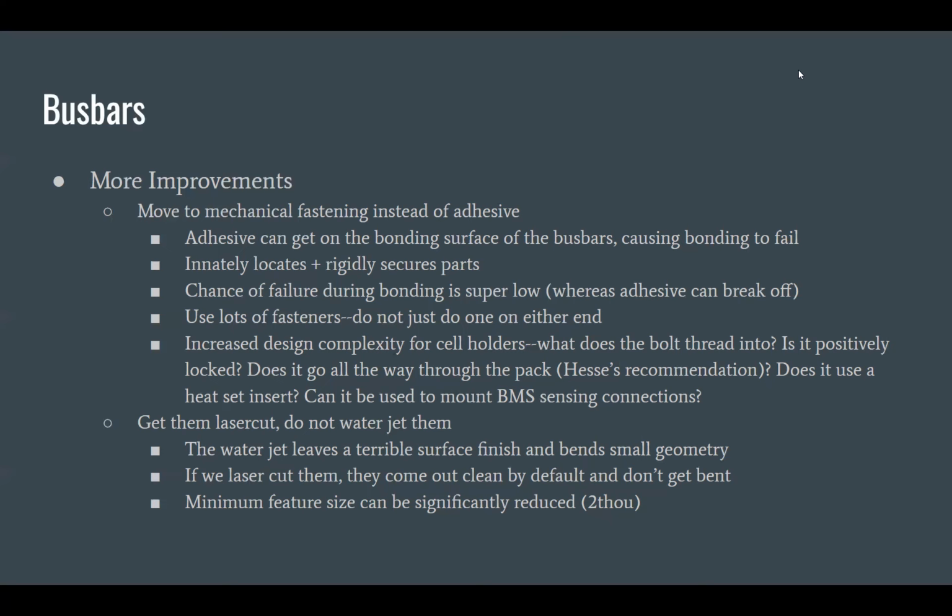And so you now have all of these new confounding factors, like, okay, well, now I have to be careful that I now have all these critical fasteners that suddenly could loosen. So I need to make sure I have lock nuts on all of them, or something like Loctite, whatever. And so I have all these individual parts that during assembly could fall apart. And then you're right, same thing.